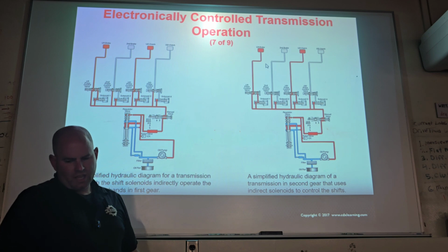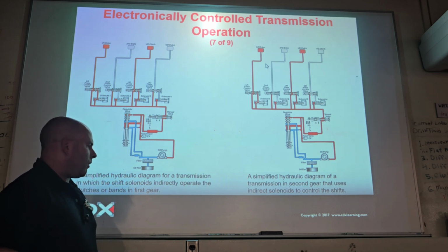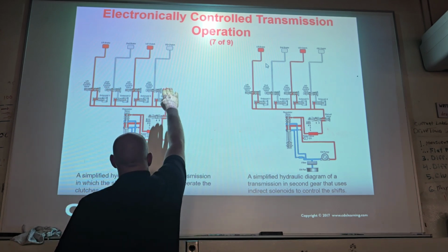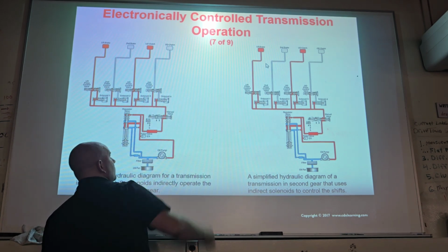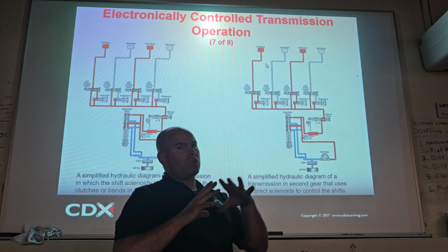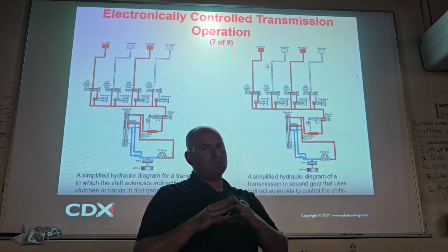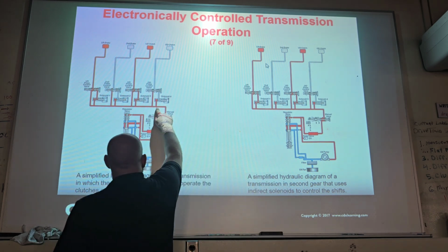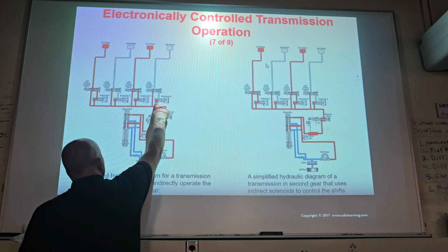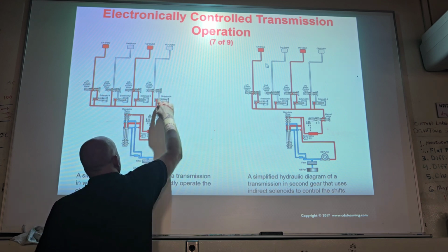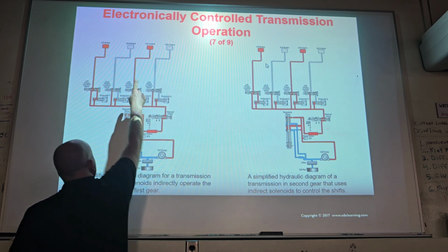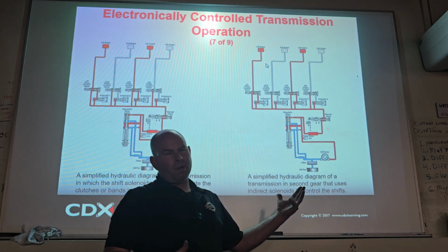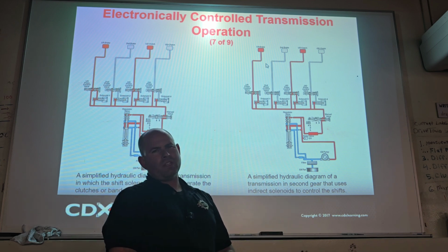All right, and so this one's again just kind of summarizing what we said a second ago, which is a little oversimplified. A lot of times, the solenoid valve actually controls a bigger valve. It's cool if the solenoid valve controls the clutch directly, and a lot of the SLs do, the linear solenoids that are duty cycled, but the small basic solenoids more send pressure. Like this solenoid S4 right here will send pressure to here, which will move a big valve, which will actually send the fluid to the overdrive or to the underdrive or to the second or to the low reverse. Make sense? So that kind of sucks, but the way we diagnose it's still really the same.